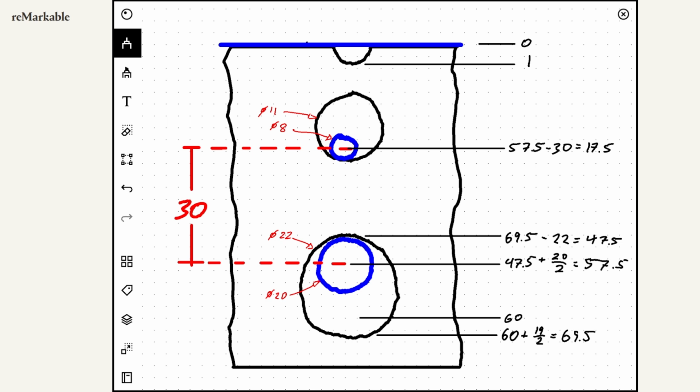Then we will jump forward to the edge of the hole, half the diameter of the virtual condition pin. I'm just going to jog this so I've got a little bit more space. 17.5. We're doing it live. Made a mistake. This should have been 27.5. You guys thought I was going to miss that. That was a test.